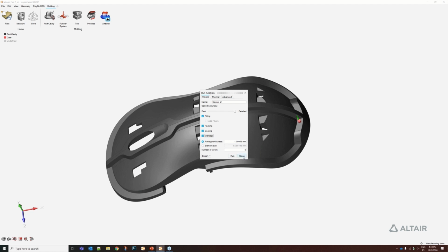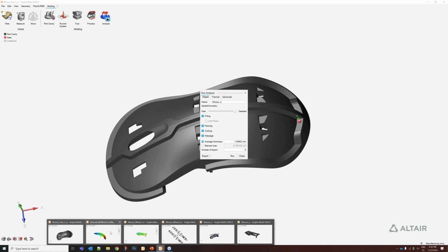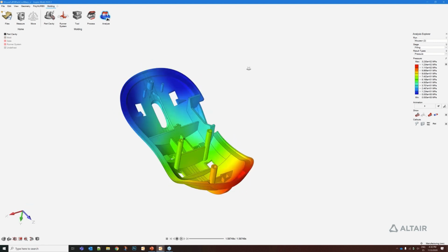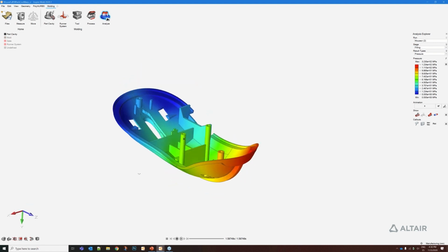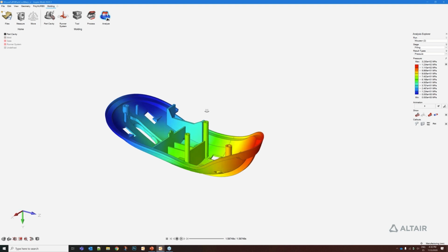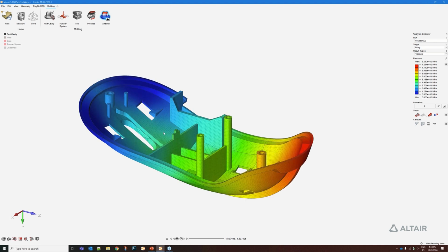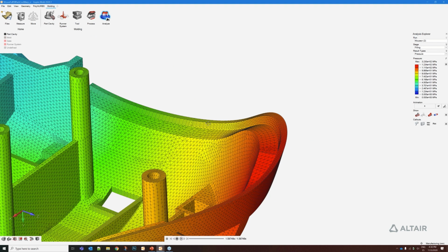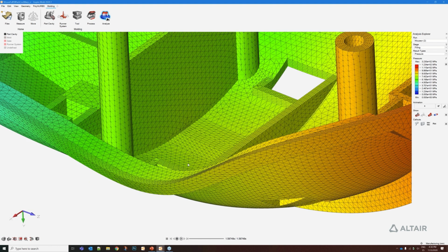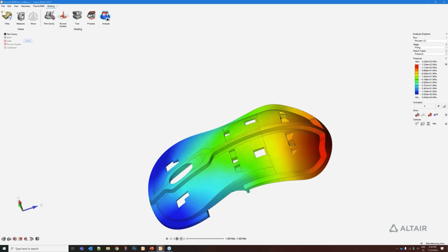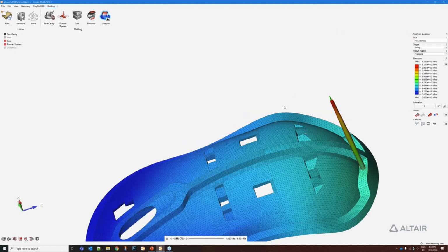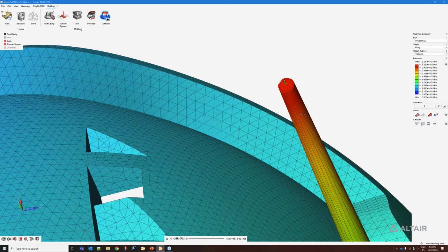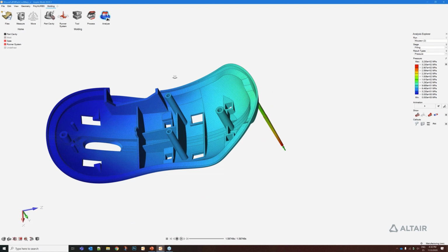Okay. One very important thing is that the mesh is automatically generated, so we don't need to define any kind of layers or any kind of assigned element size on any particular geometry. Everything will be automatically defined. And as you will see, the mesh is created considering multiple layers through the thickness. So we are ensuring 5 layers on the thickness. We are ensuring concentric boundary layers on the runners, gate, and sprue. So the quality of the mesh is extremely good, and everything is automatically done in the background.